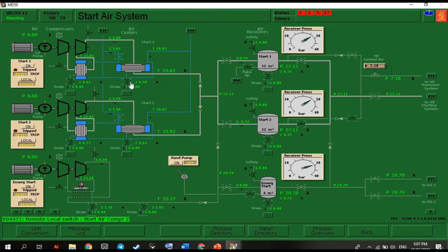So you need to drain these valves here. It is optional, but you can drain these valves here for a couple of seconds. Okay, then close. Then close this start air receiver. Makeup valve. Then turn on this makeup valve to supply air in our system.